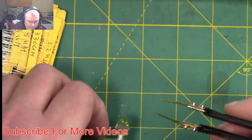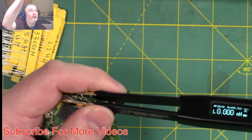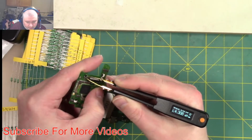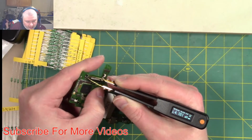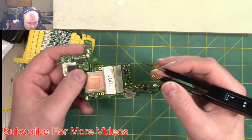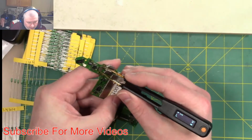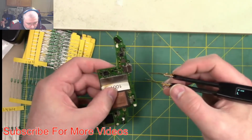Okay, so I'm going to come in here, and I'm going to hold these tweezers down. I need to zoom out a little bit, guys. I'm sorry. There we go. You can still see the meter. So if I come in here and I come up to this inductor right here and I grab a hold of it, that's going to be 4.289 microhenry. Now, that may not be the actual value of it because I'm measuring it in circuit, but that is an inductor. And if I come over here to this guy, that's an inductor. If I come up to this bigger guy, this is going to be a bigger inductor here, 1.2 microhenry. So that is an inductor.